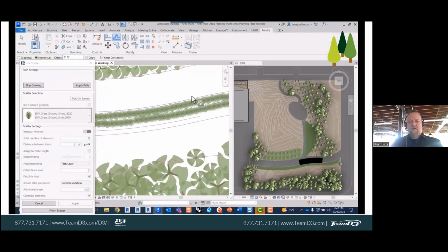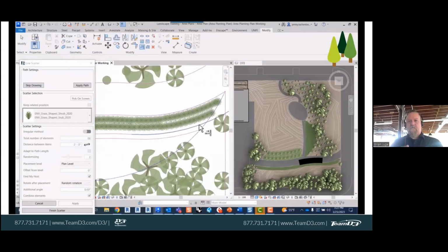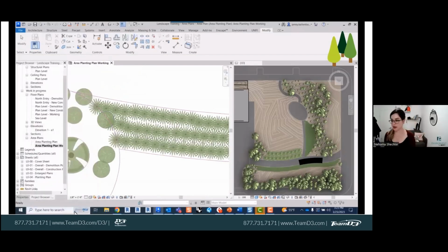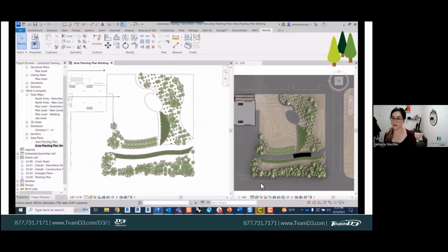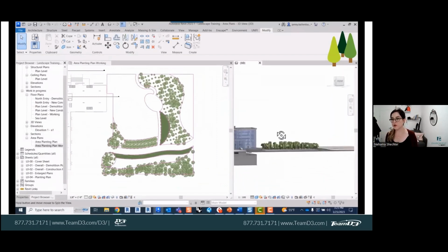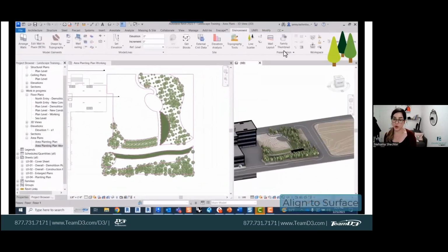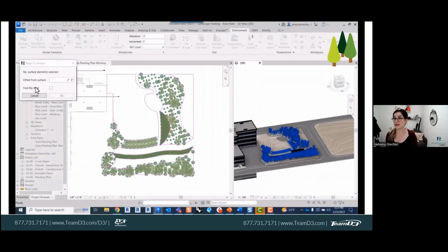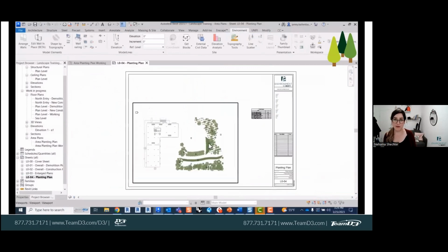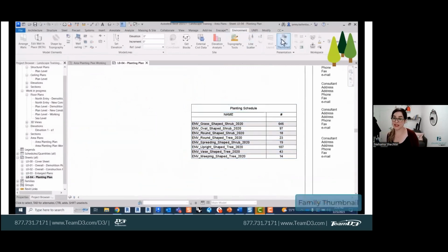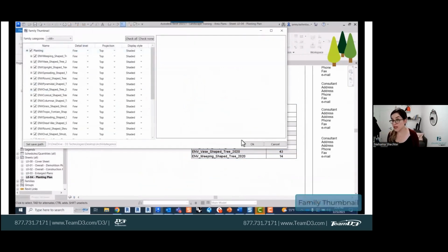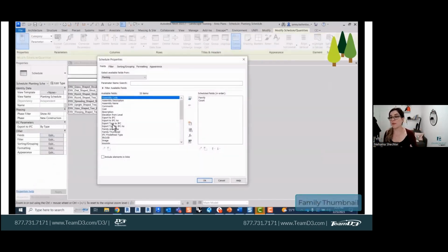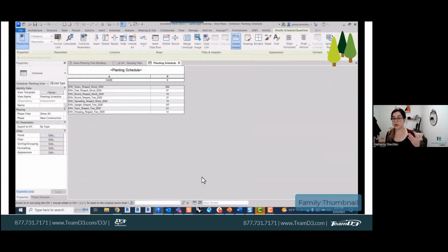Now with that area scatter, that works with more than just areas, correct? Yep. So basically, again, we want to give you as much flexibility as you want. So you don't have to use Revit areas. You can use floors, roofs, topographies, toposolids, subdivisions. Basically, every Revit element that's defined within a boundary that is some sort of a surface. You can do it with rooms. So you can use everything.